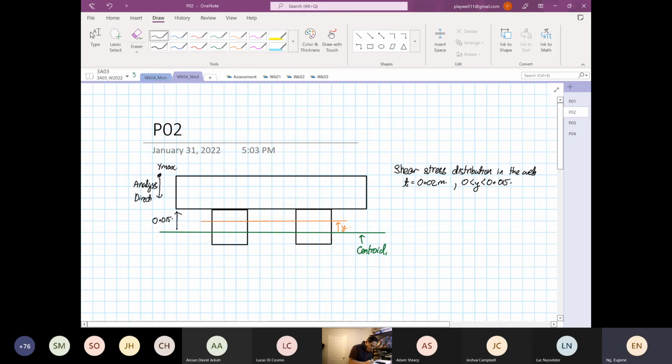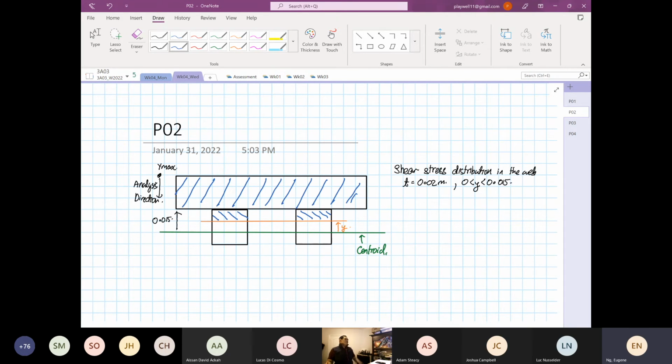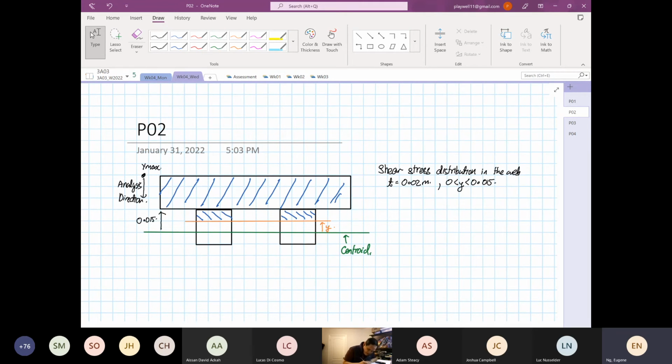The area of interest is this now. So the area of interest is, you have to include this part and this. And why? Because we have to comply with the rules that we created. The analysis starts from what? Y max. Okay. So again, it's the first moment of area that's confusing. Yes or no? Okay. So now for the first moment of area, you have Q